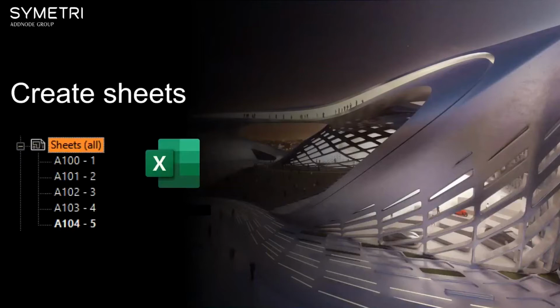So even in the world of digital engineering, at the moment, most of us are required to produce 2D drawings and documents to document our design and help communicate this to fabricators in the construction site. This script will automate the creation of drawing sheets by creating the sheet names and numbers in Microsoft Excel, and then using Dynamo to generate the actual drawing sheets. This is one of the many tasks that we all have to complete, and this is perfect for automation.